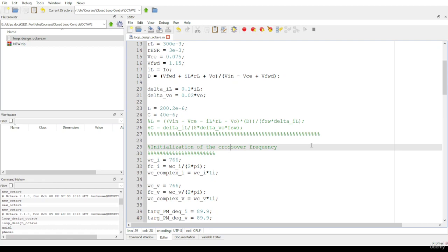Of course, you could choose other approaches, such as focusing more on the settling time and the rise time, etc. You should note that in terms of control design for power supplies specifically, you're mostly going to be dealing in the frequency domain, so you want to focus on that in your design. In other applications, such as DC motor speed control, for instance, you might be focusing more on rise time and other time-based parameters.